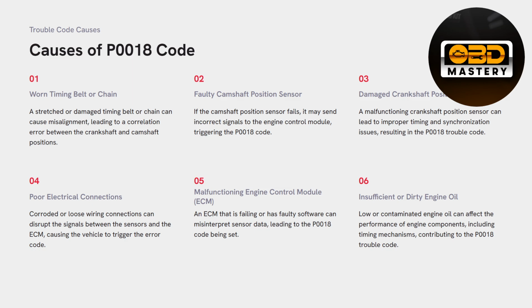Now, number two is going to be your faulty camshaft position sensor. These are pretty cheap to get nowadays, but if the sensor fails, it's not going to send the correct signals to the ECM, so it'll trigger this code. You can also get a damaged crankshaft position sensor, which will lead to improper timing and synchronization issues causing the code.